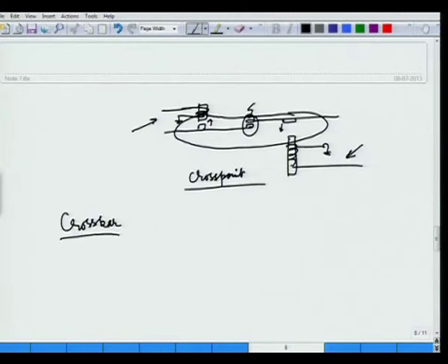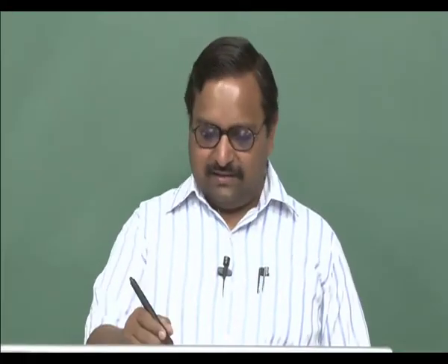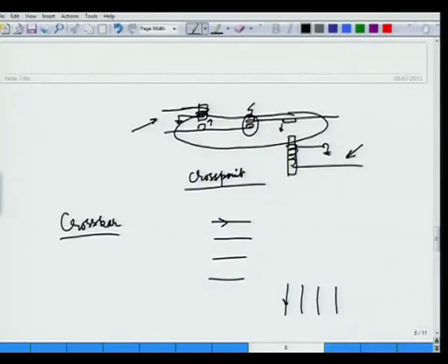So, how can you make the connections with this, that is the question. Very simple: for example, there are 4 users which are connected. Technically, these are not bidirectional lines, these are unidirectional lines. Signal comes in, signal goes out, both are for user 1. So, I will connect them together and I will use something called a duplexer. It converts bidirectional into two unidirectional lines, one where the signal enters, one where the signal goes out. I will do this for all other users.